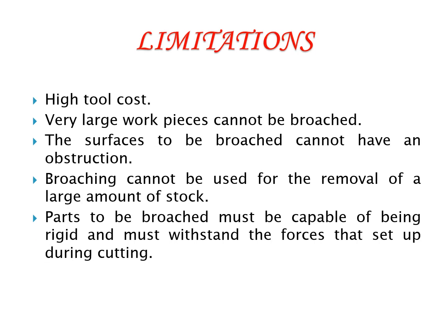So there are also some disadvantages. The cost of the tool is very high. Very large workpieces cannot be broached. The surface to be broached cannot have an obstruction. Broaching cannot be used for removal of a large amount of stock. The parts to be broached must be rigid and must withstand the forces that are set up during the cutting process.